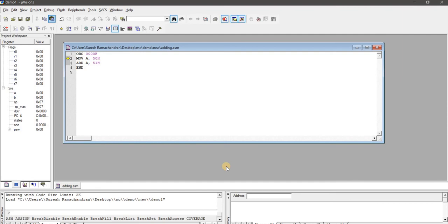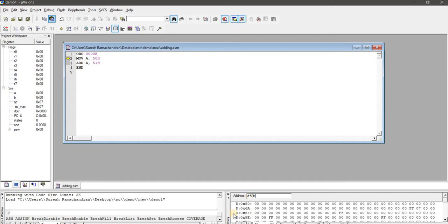You can give the corresponding address you have already used, go to this address and type D colon, then the memory address 50H. Then press enter, and it will take you to the corresponding memory line. We can see the values which are already available in the memory of the computer. You can see everything is 0. Sorry, this is 50 and this is 51. That is the memory which we are using.